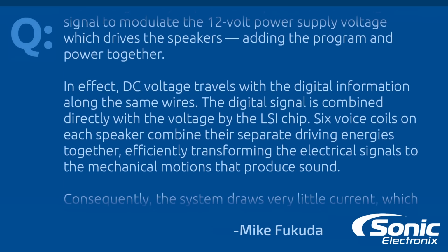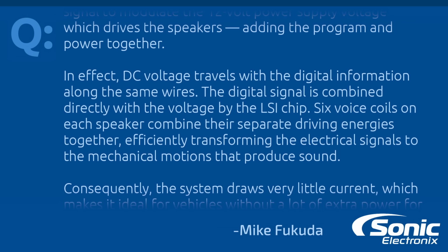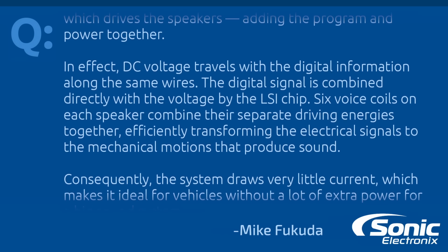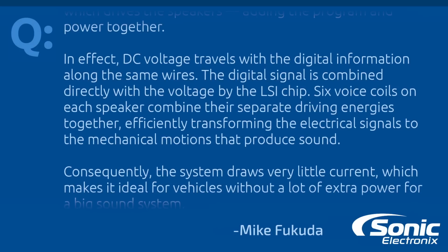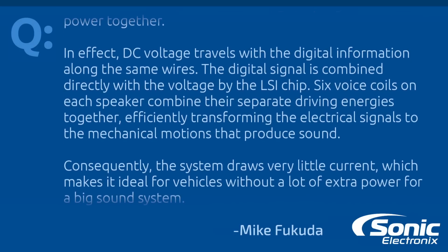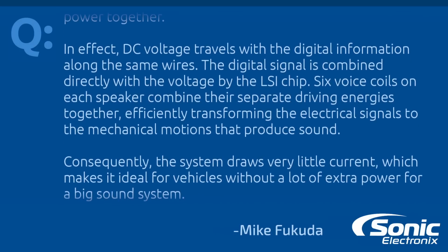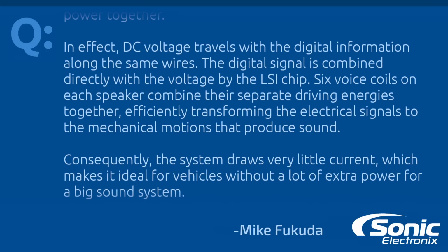Six voice coils on each speaker combine their separate driving energies together, efficiently transforming the electrical signals to mechanical motions that produce sound. Consequently, the system draws very little current, which makes this ideal for vehicles without a lot of extra power for big sound systems.